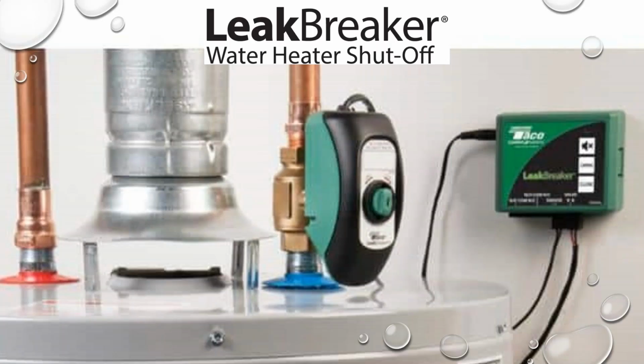So here we see it installed on a water heater. If you're putting in a new water heater, very simple. You just screw it right onto the cold water supply feeding into it, and then bring your cold water supply in behind that. We install the controller on the wall, run the sensor, drop it on the floor underneath the water heater, and you're protected. So if you've ever had a water heater failure where it leaked in your home, and you're putting in a new water heater, this is an easy peasy installation happening right then and there.